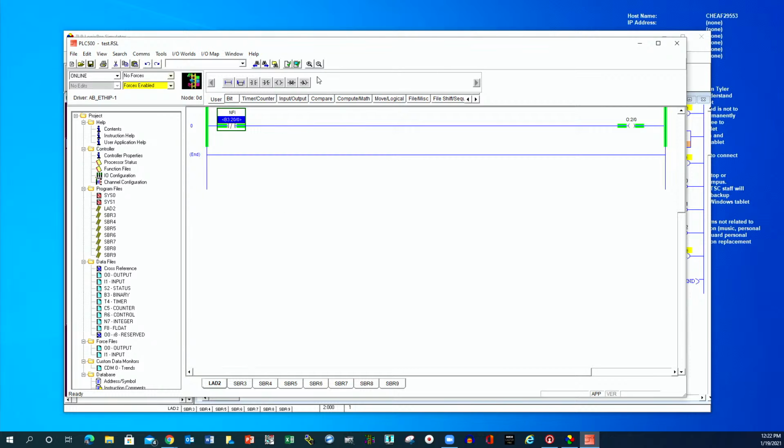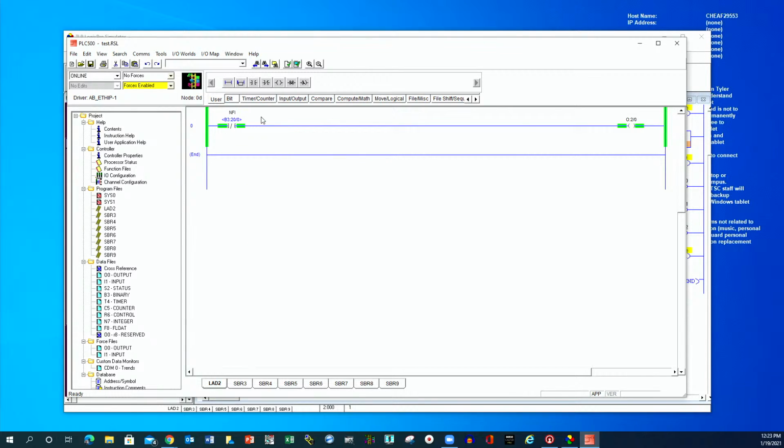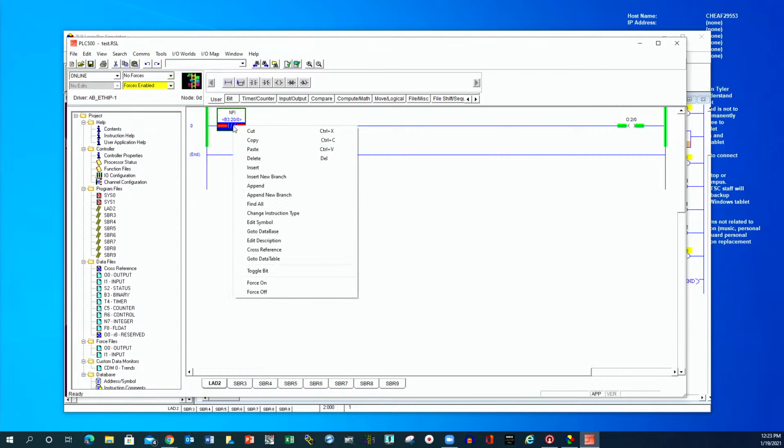So it's never false. It never turns off. It's always on. So that's an option. You can also have one that's never true, the exact opposite, that simply never comes on. That is a way to troubleshoot as well, but that is not the proper way.